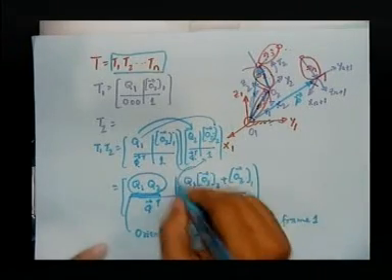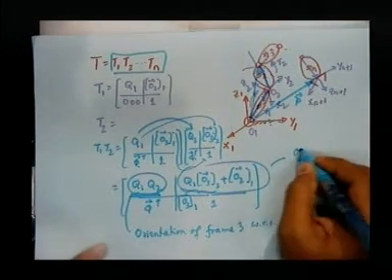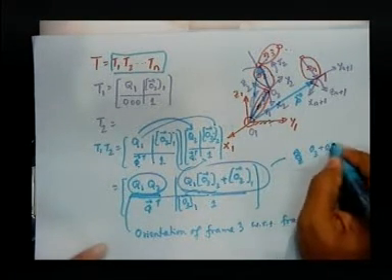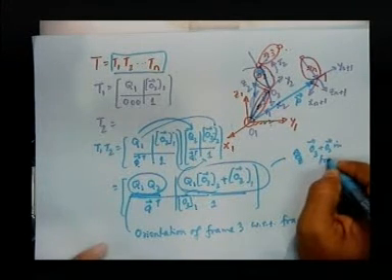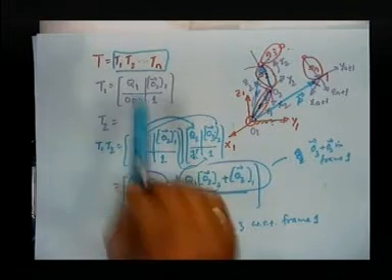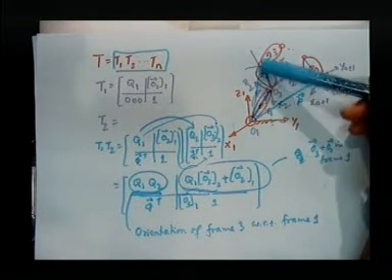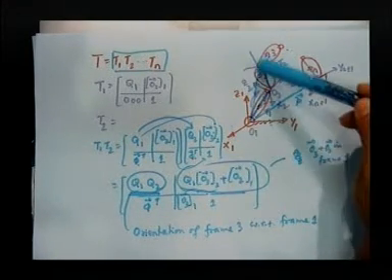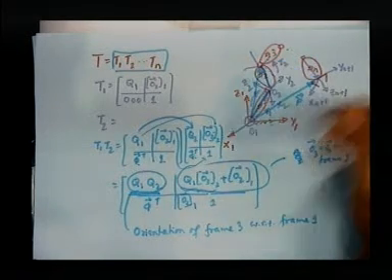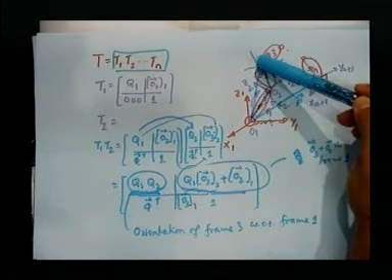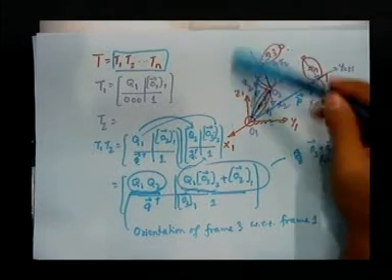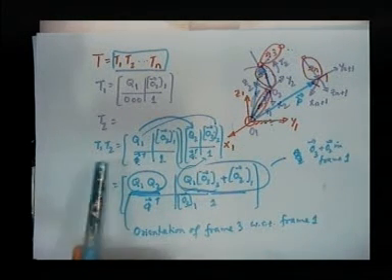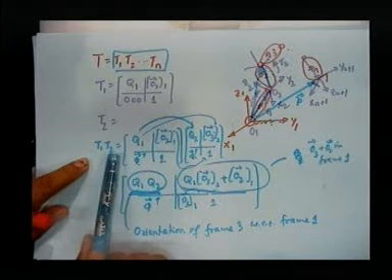So, this component together, if I give it a name, is O3 plus O2 in frame 1. So, in effect, when I multiply T1 and T2, I can get the information of where this point is for the 2 link robot system. I can get from here the position of this point and the orientation. These are the two things I require to know how to move a body from one frame to another frame. Now, notice here I have shown you in the transparency which will go back, I can do either T1, T2, but what are my results?